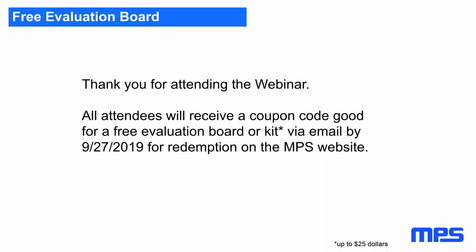How about a recommended hotspot on the package when it comes to measuring the thermals? The hotspot you get is typically in the middle of the switching IC. If the inductor is very small, the inductor could also be a hotspot. But that should be the only hotspot in a switching power supply. If anything else gets hot, then you had made a pretty poor design. So typically the switcher and the inductor are the two things. And most times the IC will get hotter than the inductor if you have a decent design.